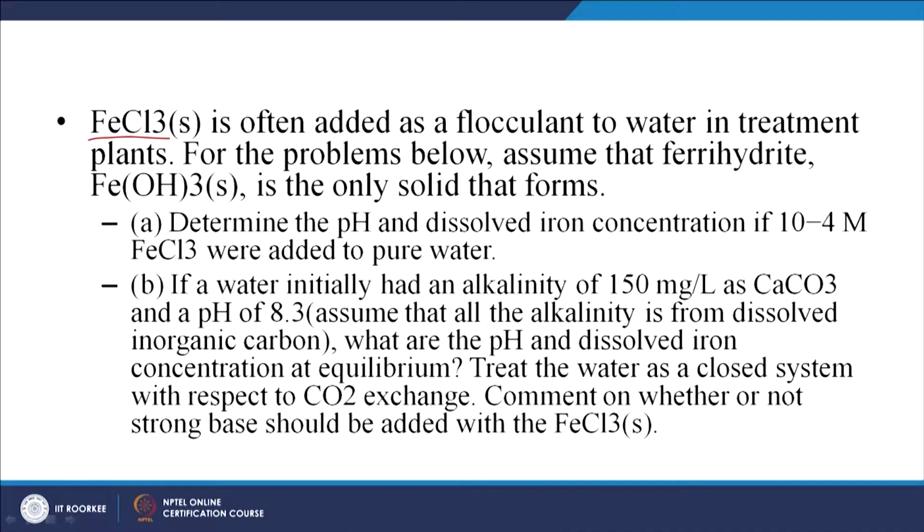Here we have FeCl3 added as a flocculant. This is a common flocculant added to water in water treatment plants. We also say that the controlling solid is ferrihydrite. That's information you always need. Why do you need it? Because the solubility product, not the dissociation constant, depends on the kind of the controlling solid.